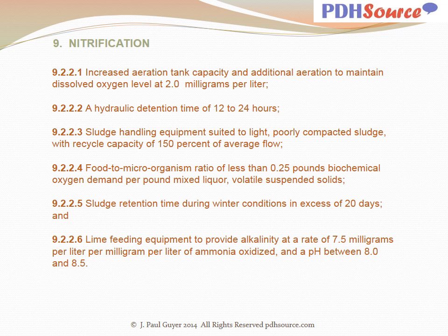Sludge retention time during winter conditions in excess of 20 days, and lime feeding equipment to provide alkalinity at a rate of 7.5 milligrams per liter per milligram per liter of ammonia oxidized, and a pH between 8.0 and 8.5.